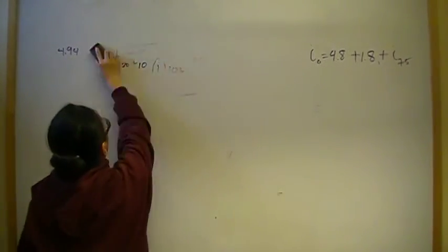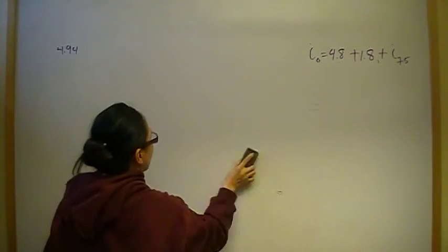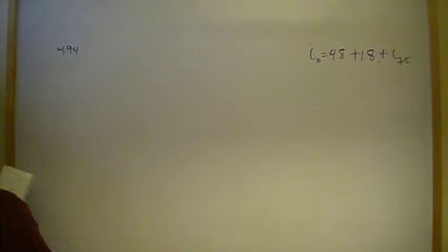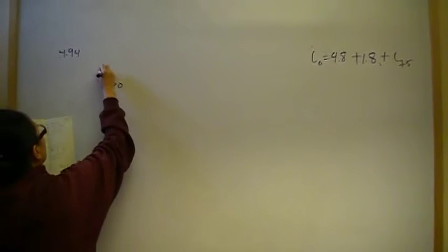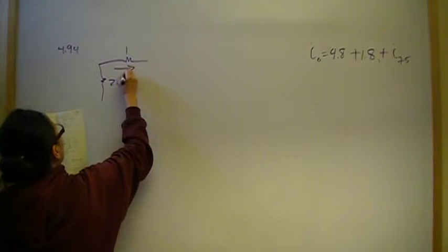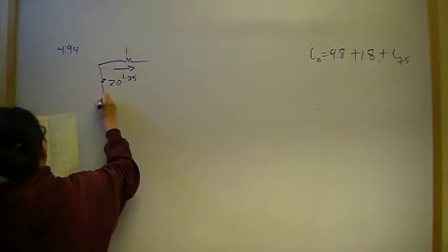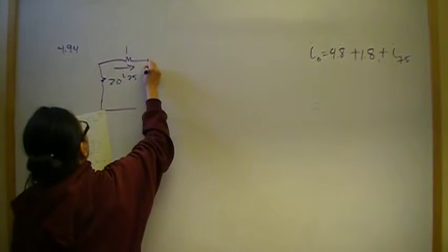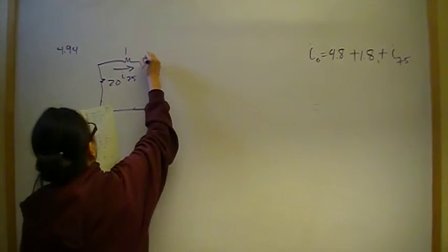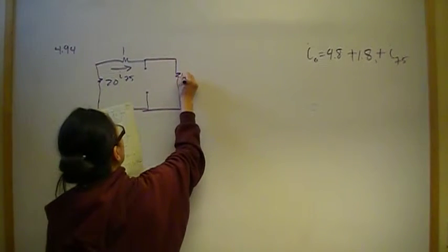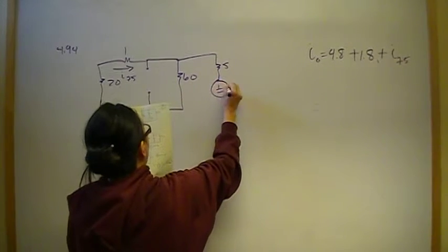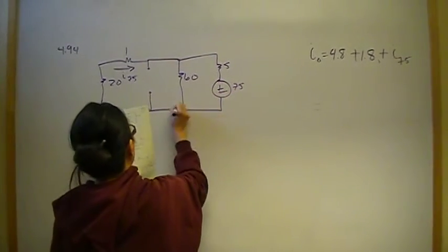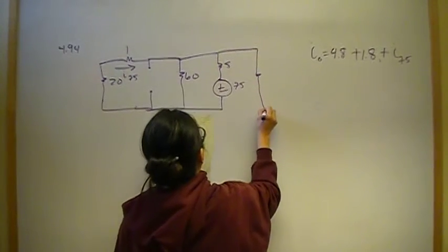All right, the last piece is to consider just the voltage. So now, again, we restore this, we open up the current sources and leave the 75 intact. Here's my original. So we open the 6 amp, that means our circuit starts here with 20. And then we got the 1 here, we're looking for I-75. We open the 10, and then we have 60, and we have 5, and then now we're looking at the 75, and then we got 30.